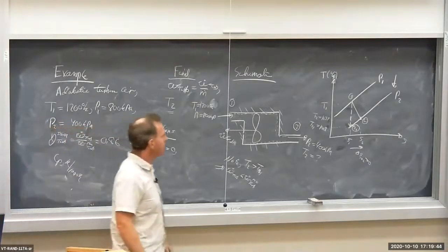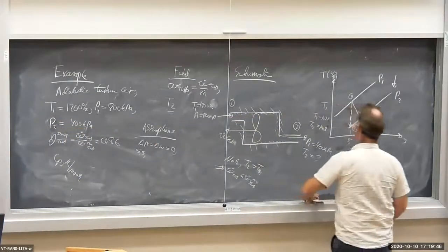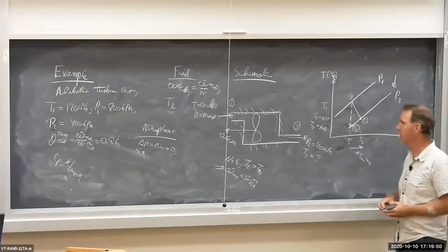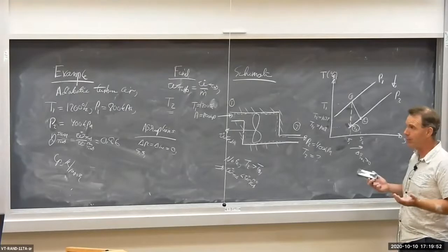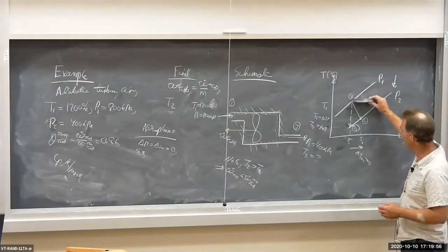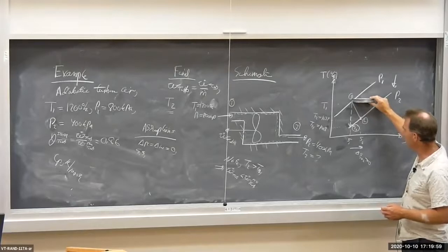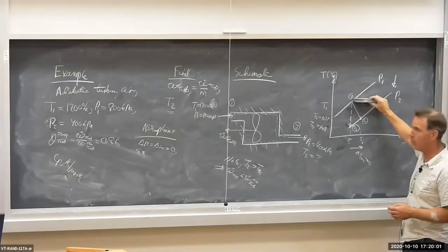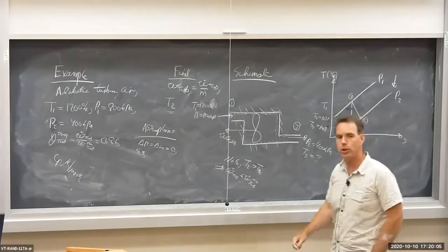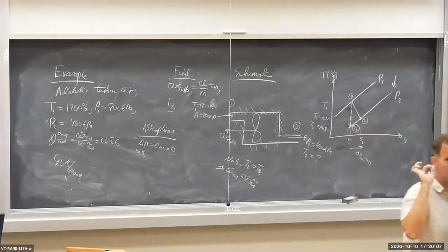In theory, I don't mean to get extreme here, but if the real device is so irreversible that its isentropic efficiency were 0, then in theory, the outlet temperature could be equal to the inlet temperature, if it's not extracting any work. So an extreme case would be a turbine with an isentropic efficiency of 0.